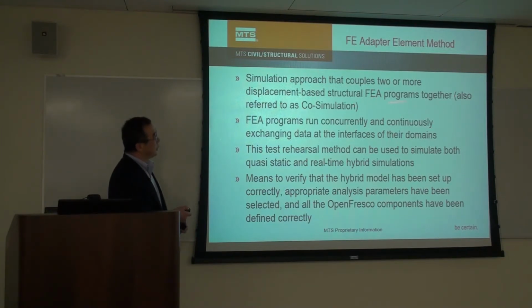So this is one of the core simulation methods. You use one FEA package to simulate one substructure, maybe the numerical substructure, and then you use another FEA package to simulate maybe the physical substructure, and these two FEA packages run concurrently and simultaneously and simulate the real test.